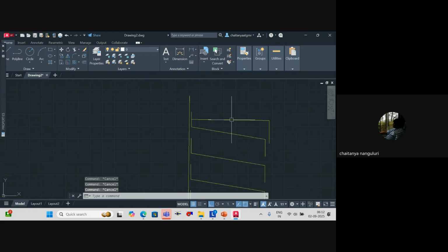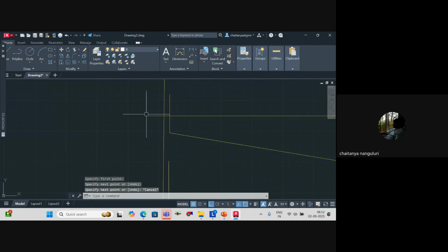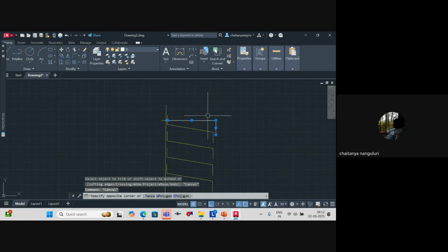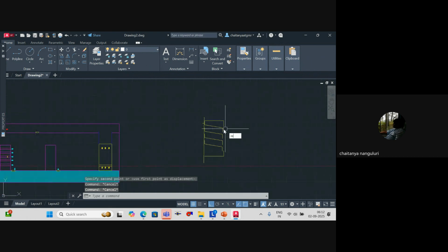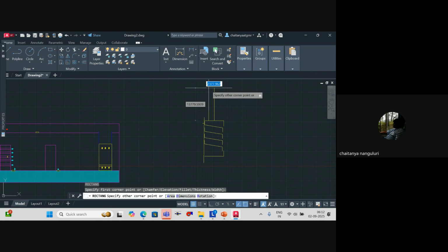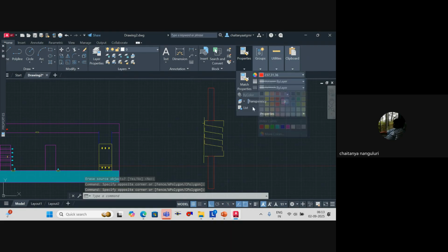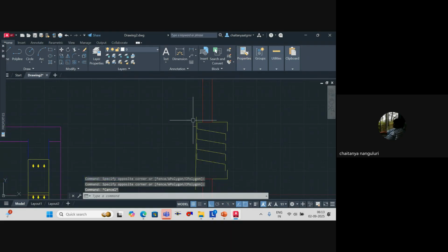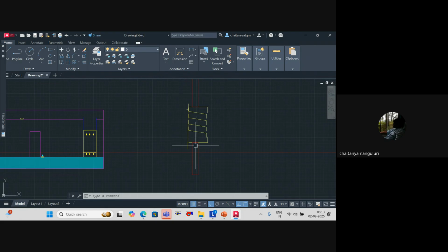The only thing is the sealing of this particular corner, it needs to be done properly. If that's not done, no one can help you. Understood? So at this location, you have this particular wall surface, whatever it is, that needs to be sealed properly. If you have a civil wall here, that should be done by the civil team. Understood or not? Because I've seen a lot of places where afterwards you'll find leakages because of the gap at this location. So when you install a louver, you should make sure that this is sealed properly. You have to do grouting or anything with GPT or any other chemical.